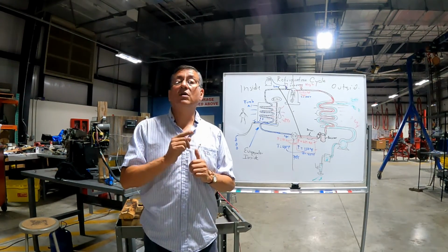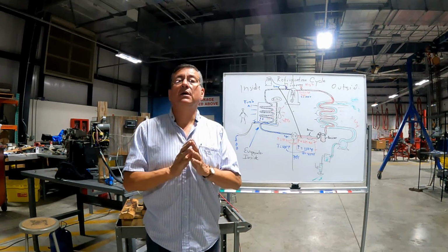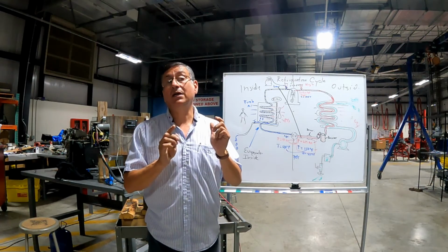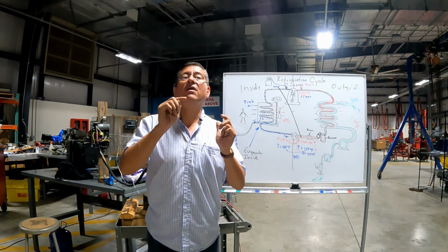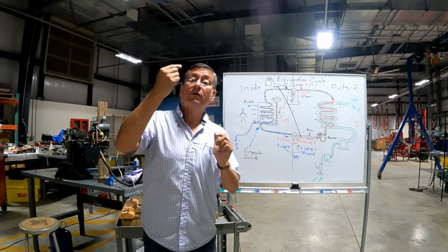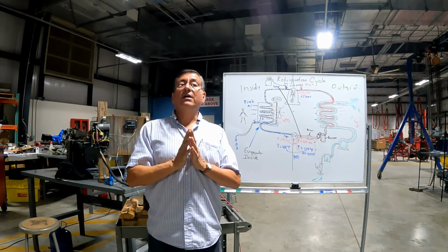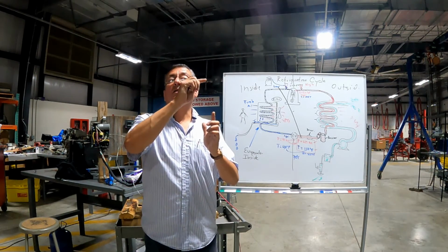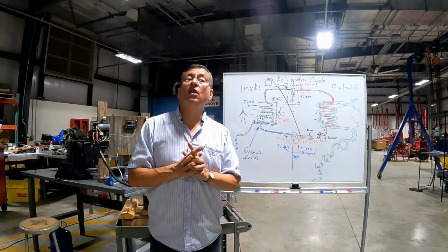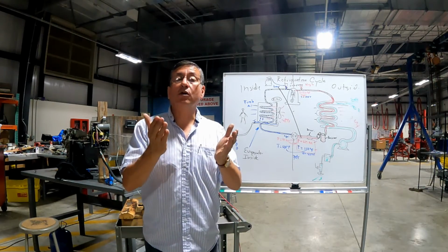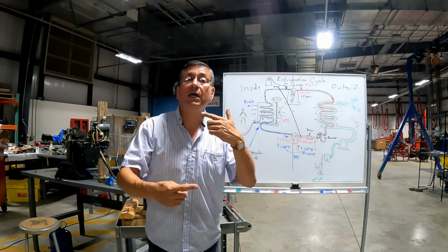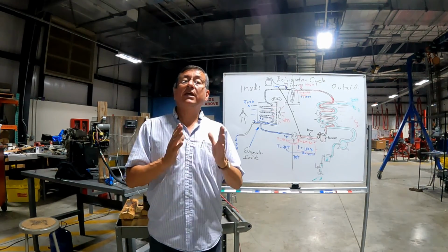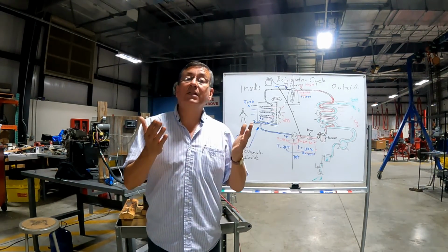And on the other side you have liquid at low pressure and low temperature. That liquid enters the indoor coil and starts to evaporate. At the output of the indoor coil you have a vapor, and that vapor enters at low pressure and high temperature into the compressor, and the cycle continues again and again and again. In other words, the secret is, of course, the refrigerant.